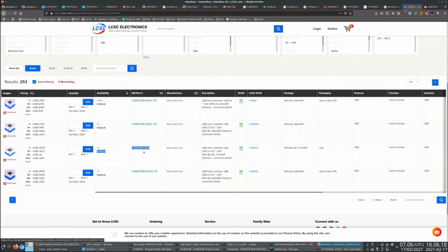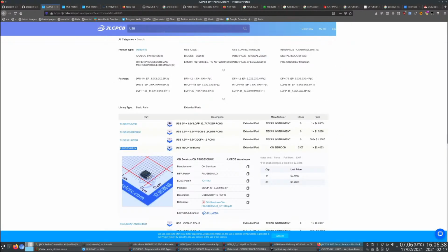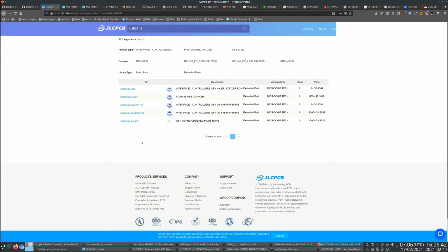Anyway, it might be fine. The SBU swap also happens when you flip the port anyway, so that's not necessarily a problem. It would just be kind of cute to be able to do it internally. But if the hub doesn't support switching those without a complete reset, that's not a nice option.